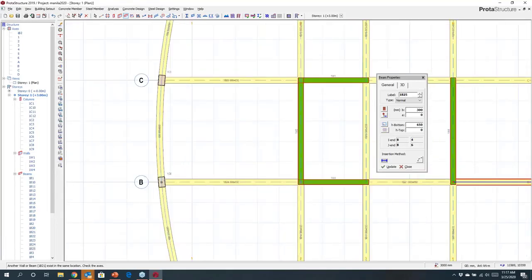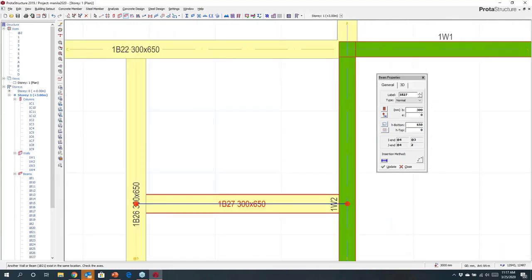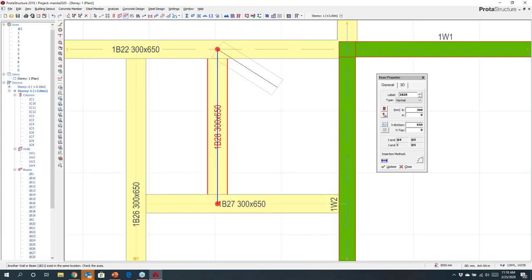It's smart. It knows that they're there. There won't be any overlapping. And you can just use intelligent snap points to come in and create things quickly as you go. Now, if you have certain set out, if you hit F2, you can type in the exact coordinate that you wish to create, and then it'll pick up handy points like quarter point, midspan, that perpendicular point, and you can create that element.